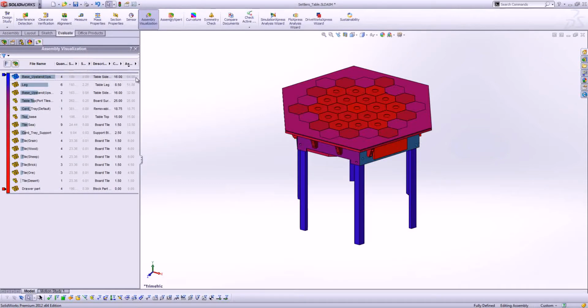So we've now got the most expensive assembly item is not the most expensive individual item. And that's going to be quite important from a manufacturing point of view. You quickly find out that money saved in the base upstand part is worth more than money saved in my tabletop part, which is the most expensive individual item, because I'll save it 4 times. So very quickly we can start to narrow down on what's going on.